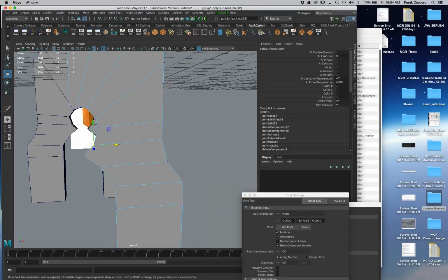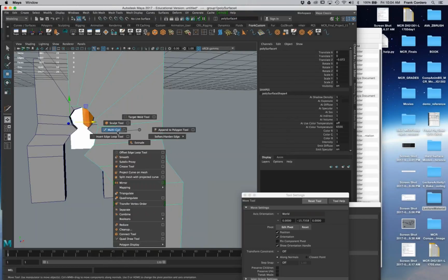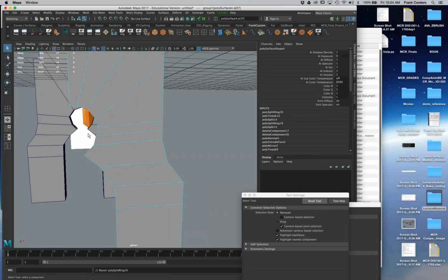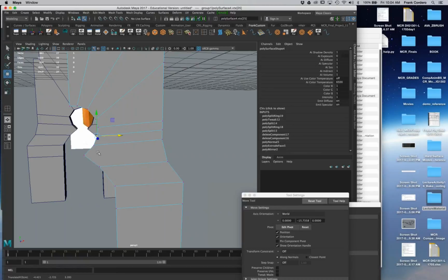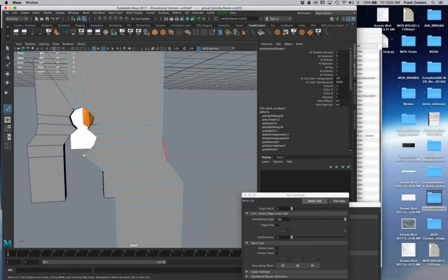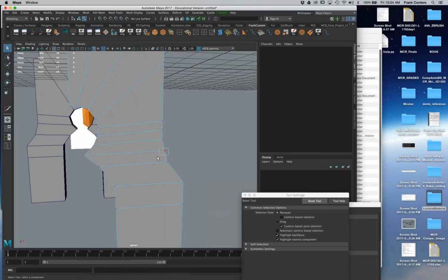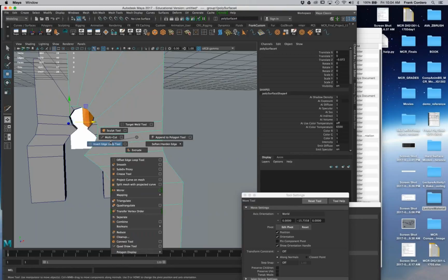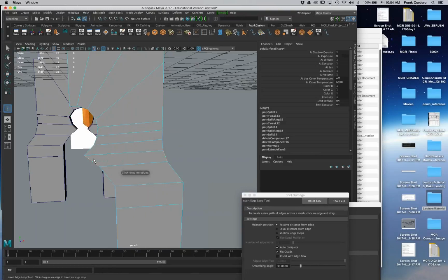All right. And then this part, I'm going to say, you know what, probably needs a couple of extra edges. Insert edge loop. And then I'll just go in here. And then, again, now I'm starting to kind of commit to the shaping. Let's go over here, multi-cut tool, because it looks like I've got an end gun here. But that's okay, though, because I need the extra edges on this side. So now, go over here. So now we're starting to kind of really get in there and commit to the silhouette. So I might need an edge there, and I might need an edge.